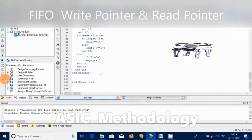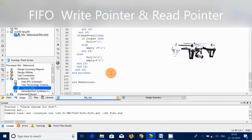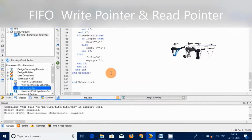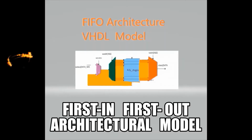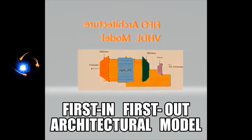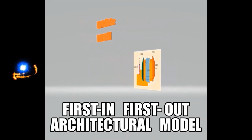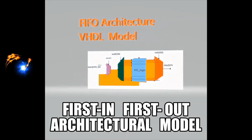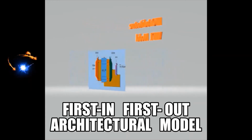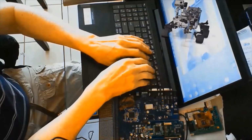In the dual port RAM model segment of the FIFO, a write counter addresses the write side of the RAM and a read counter addresses the read side of the RAM. The control logic updates the write counter at each write of data into RAM, and the read counter every time data is read from RAM.